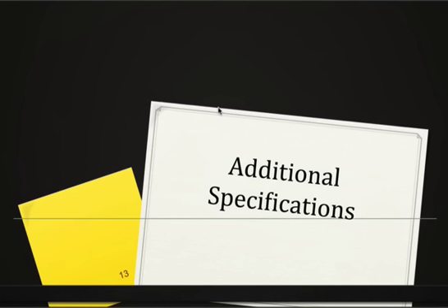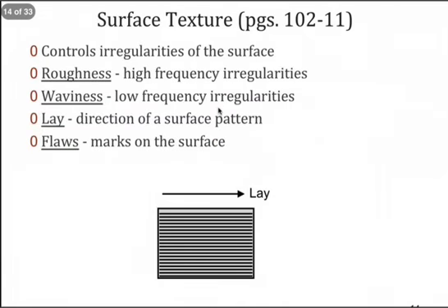And secondly, you need to make sure that everything is clear about the use of dimensional tolerance versus geometric tolerance. By that I mean if you are controlling position with a position geometric tolerance, you should not be controlling position with a dimensional tolerance. Again, they could be in conflict. Same thing with angularity. If you are controlling orientation with some type of orientation tolerance, you should not be controlling that with a dimensional tolerance on the angle. Okay, enough said.